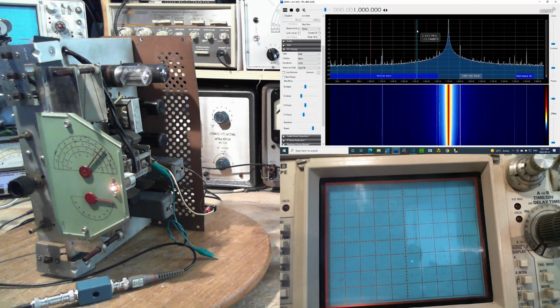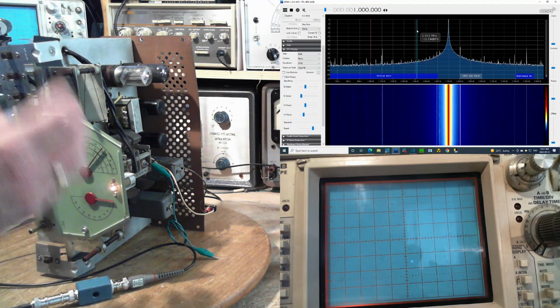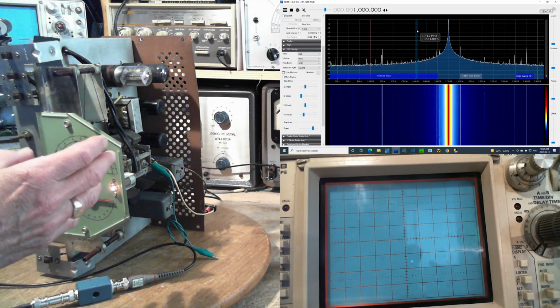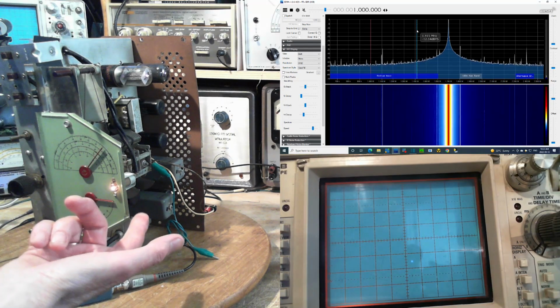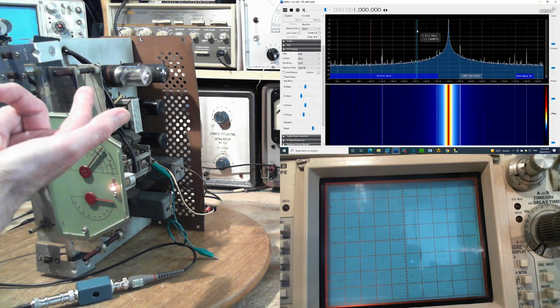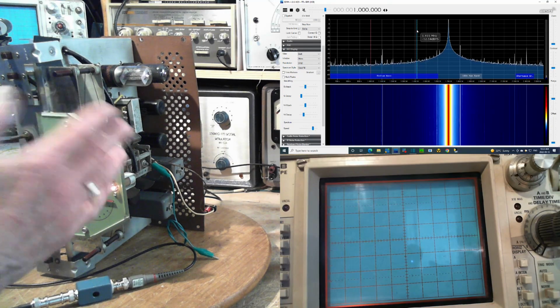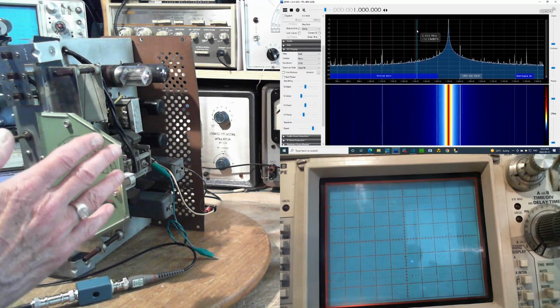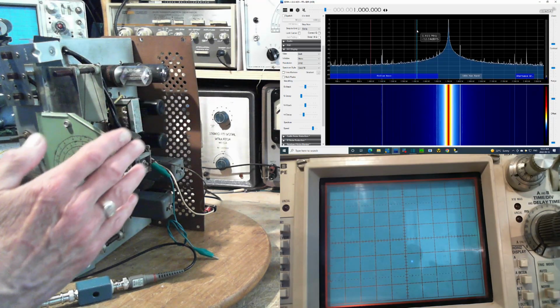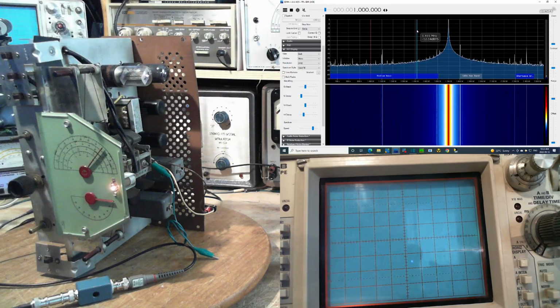When I throw that switch, there's a moment where the power is broken to the radio completely, when I go from dim bulbs to straight power. And during that moment, I think what we saw was the heater cooled down enough that the local oscillator weakened and then came back up when the heater recovered. Ultimately, I think everything's a little bit stronger now, but the frequency did not change one bit.